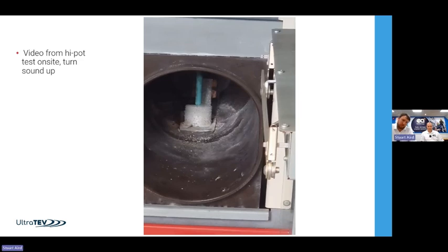Just on the surface of the insulation there, that's starting to arc away, and each one of those sparks is doing a little bit of damage. So it's some energy release that's eating away at that insulation. And if you could zoom in on that, you'd start to see a treeing effect. And that treeing effect is why you get a much higher number of pulses per cycle, number of events per cycle, and you get an internal discharge. You've got multiple discharge points going on at any one time. And that's heading towards earth points and eventually to a flashover.